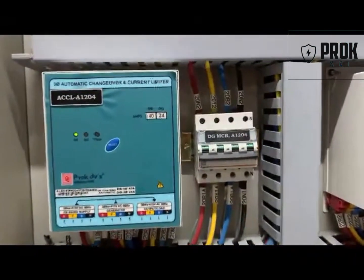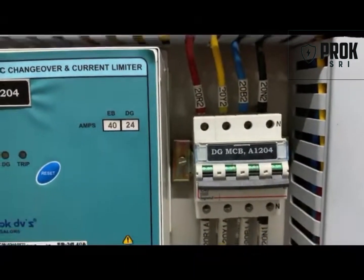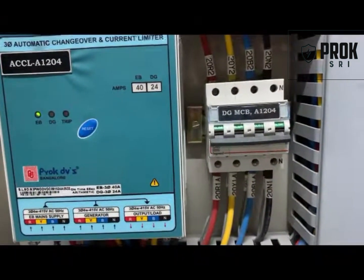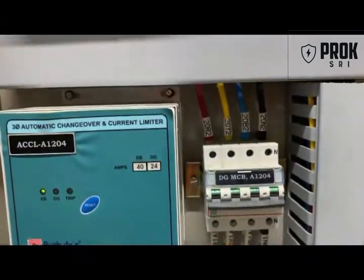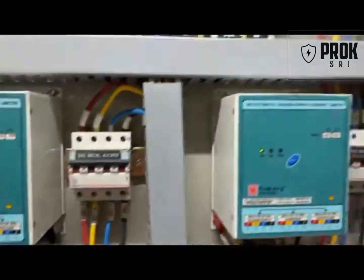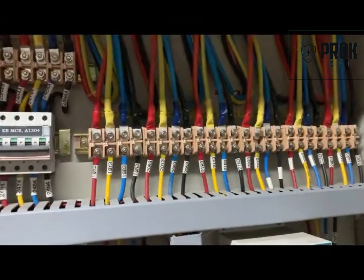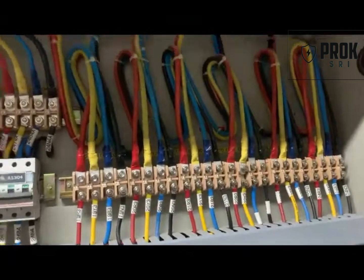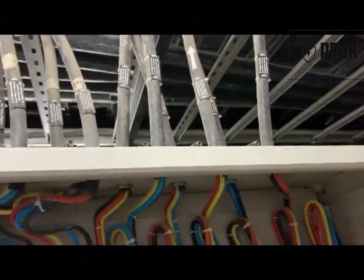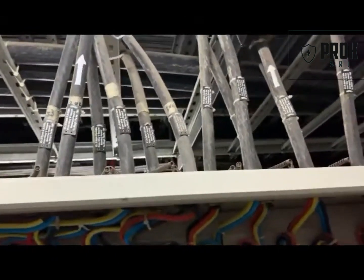Similarly, a set of wires from the DG comes to the DG MCB assigned for flat A1204. The output of the MCB is connected to the ACCL input for the generator. Here is the output of the ACCL, where it will connect to the load. The load wires are connected to the terminal block. From the terminal block, through these black wires, it goes to the particular flat, which has been assigned 5 kW on EB and 6 kW on the DG end.